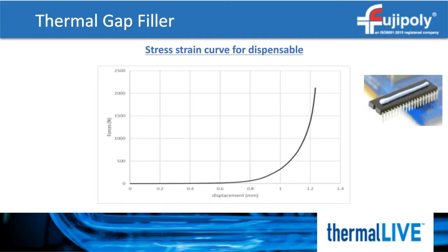In the graph, we started with a 1.5 millimeter gap and compressed our SPG form-in-place with the goal of compressing it as much as possible. You can see the material does flow under compression and gives us little to no stress, but at some point, the stress climbs dramatically. We can never totally compress it down 100%, obviously. In fact, you can see that well before that, the stress climbs dramatically. Form-in-place materials are very easy to compress, but the fillers will eventually act as a hard stop.